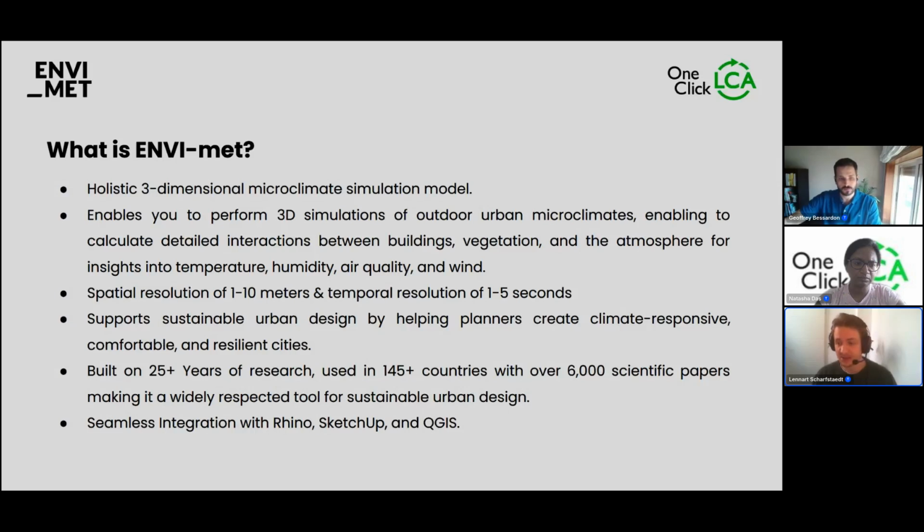So we talked about microclimate. So it's a very small-scaled inspection of climate processes, and so in our tool we need a very high spatial resolution. This revolves around 1 to 10 meters usually with ENVI-met simulations, and we have a temporal resolution of 1 to 5 seconds. So a usual case with ENVI-met is to simulate a whole day in a certain climate with a certain weather. And every second of this day is being simulated, and on the basis of that, we get a very detailed picture of the actual microclimate throughout the whole day.